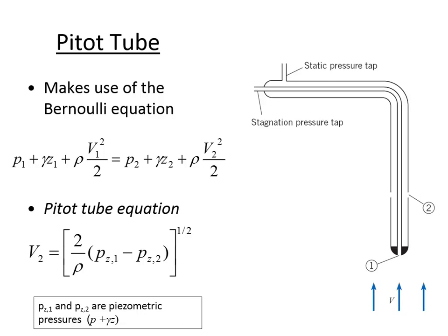What's happening there is that there's a certain amount of energy in this air. If it's being used to measure the velocity of air, then some of the energy is in the velocity term, and all of the energy that exists as velocity at 1 gets transferred into an increase in pressure. So if you've got a certain amount of energy, then all of a sudden the velocity head goes away. That velocity has to go into the pressure. So there's more pressure at 1 than there is at 2. At 2, you're not really measuring the velocity at all because it's not causing the stagnation.